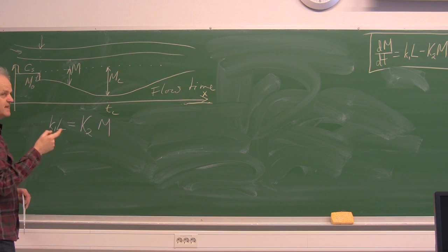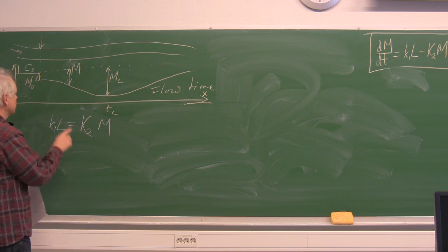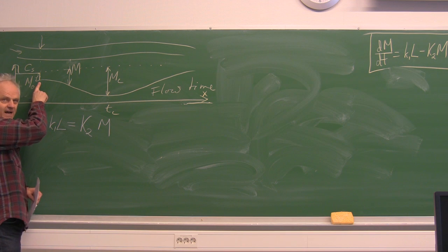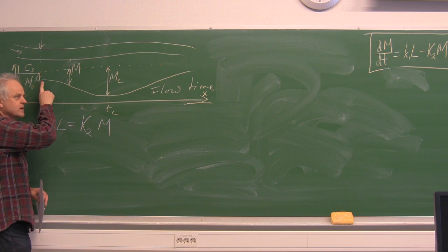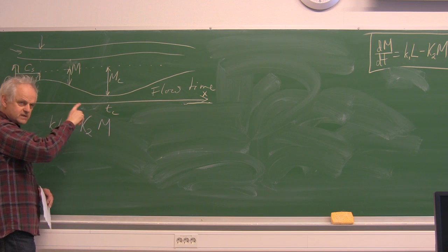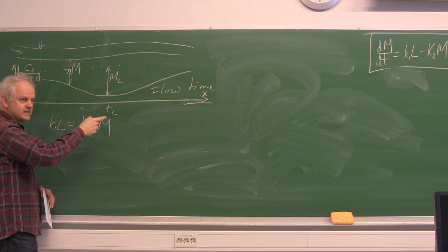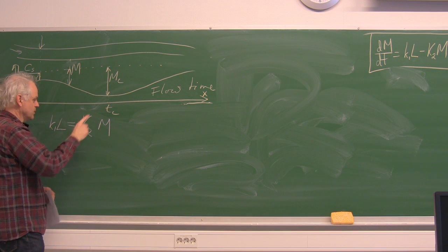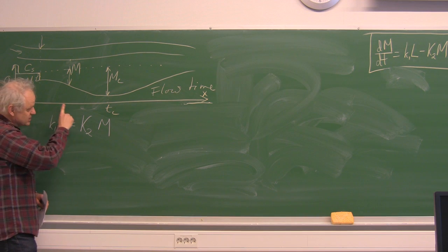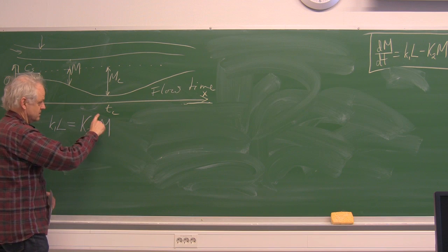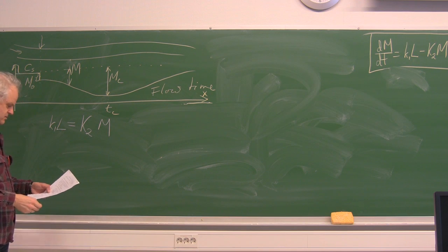L is the BOD. And the BOD, of course, is the stuff that we add here as discharge, but it is broken down as we go. The reason why oxygen is consumed is for the microorganisms to break down L. So in other words, L is changing with distance, called time in our equation.